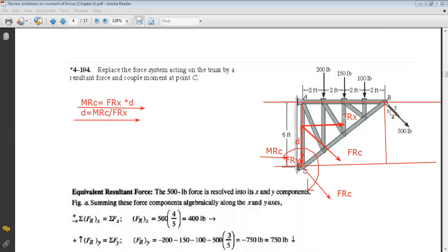You know why? Because you are in a 2D problem. In a 2D problem, look, how is your moment vector here? It's perpendicular to the screen. Your moment vector is perpendicular to the force. Whenever your moment and force are perpendicular, then you can remove the couple by displacing the force. But in 3D, you have the possibility to end up with a moment and a force resultant that are not perpendicular. In this case, you can only reduce to a force and moment that are parallel. In 2D, you always get them perpendicular, so 2D you can always replace by a single force. And this is a 2D problem.